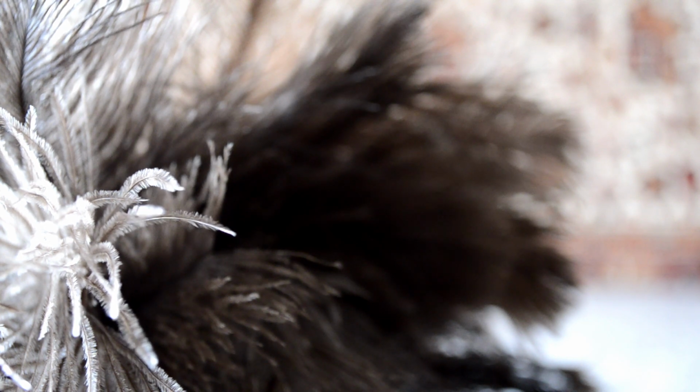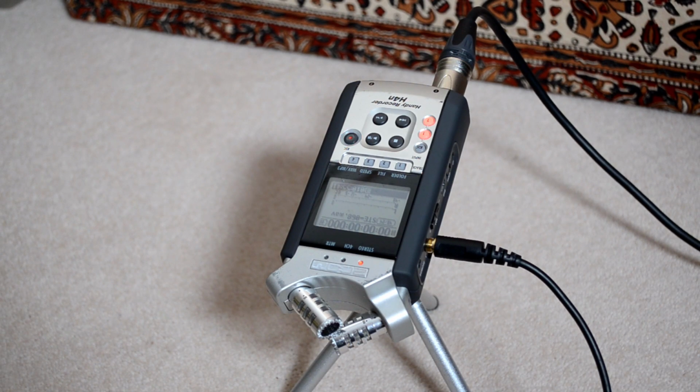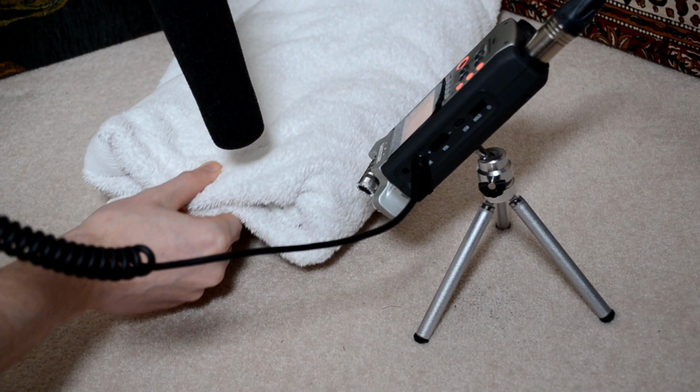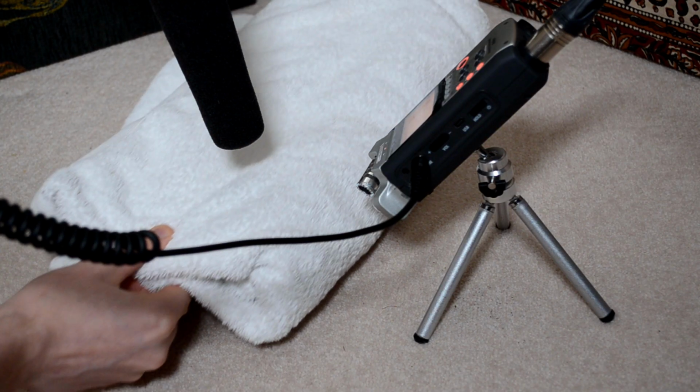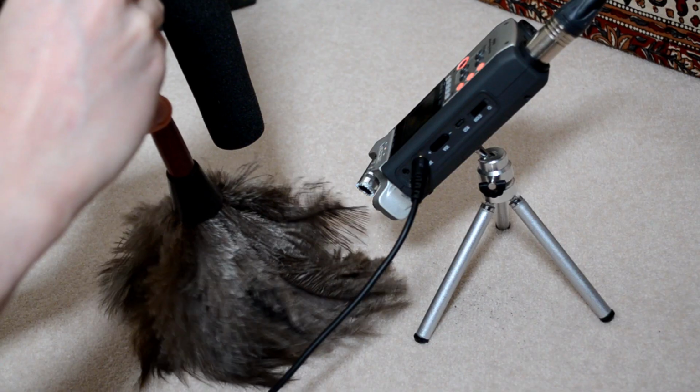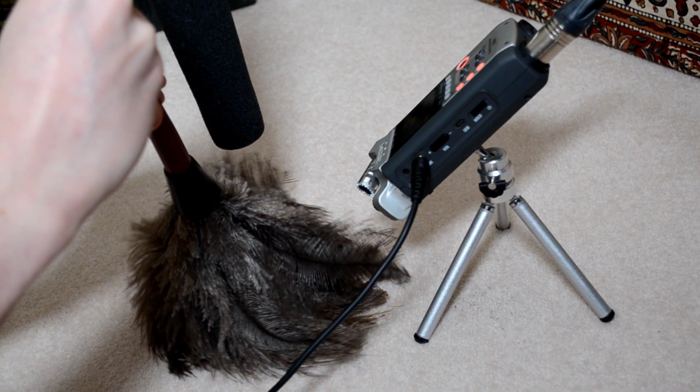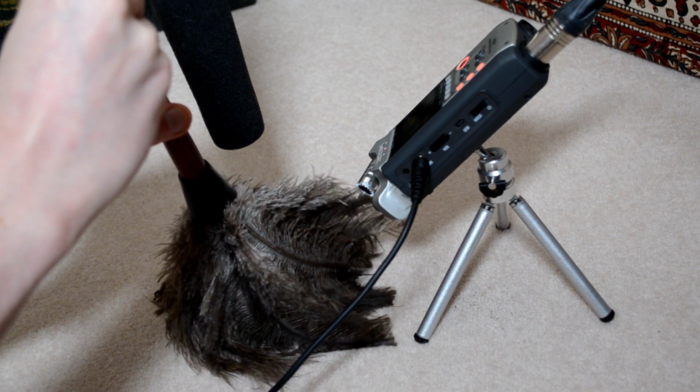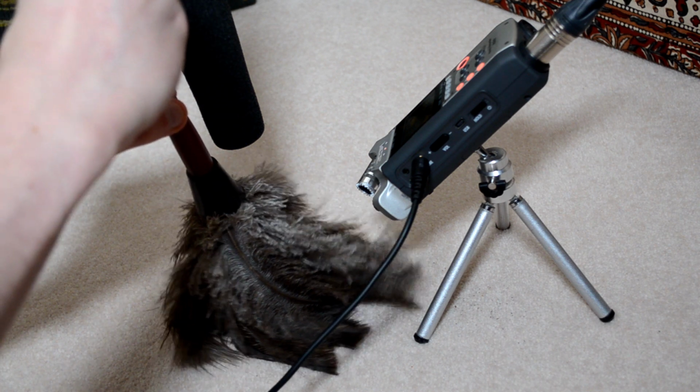Due to the nature of these items, I will be driving input gain levels quite high, and it's likely that the noise floor will be significant as a result. However, this is not a concern because it is one of the few situations where noise is actually what we are looking to capture, so a high noise floor actually works in our favour to a degree. Here are some clips containing the original recordings of both.